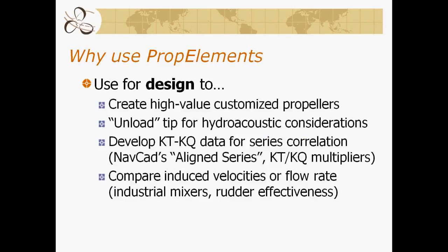We would use PropElements for design if we want to create high-value customized propellers beyond just the scope of the conventional systematic series propellers. If we want to do things like unloading a tip for hydroacoustic considerations, and we'll see that here in just a minute. If we want to export KT-KQ curves for a variety of reasons, or if we want to compare induced velocities for things like industrial mixers or calculation of induced volumetric flow rates, which can be used in studies of rudder effectiveness, for example.